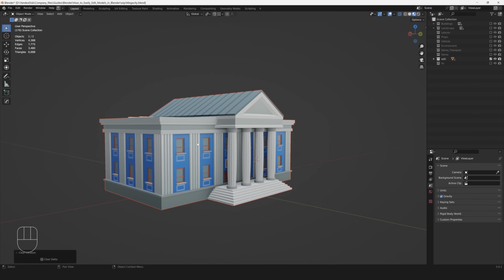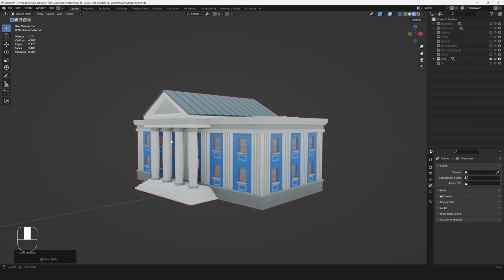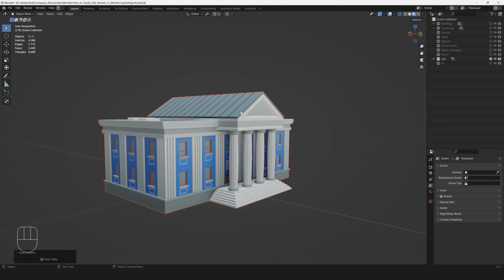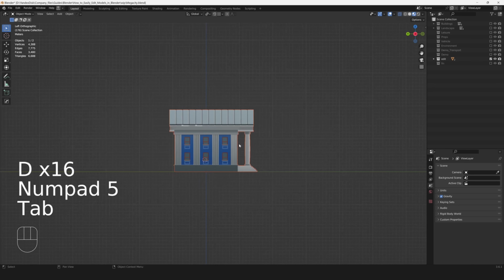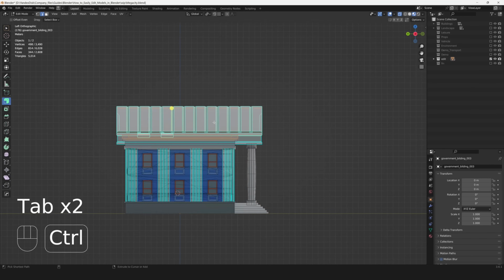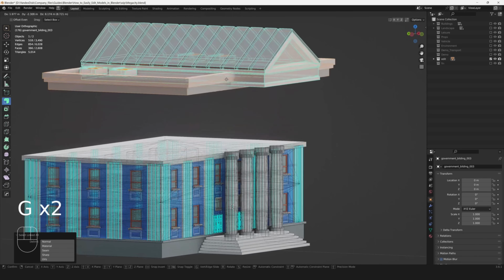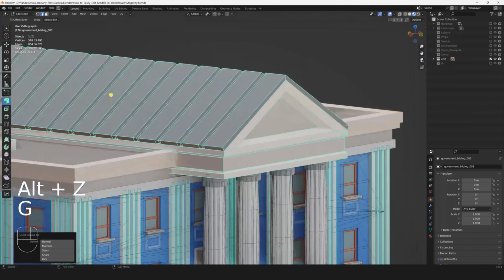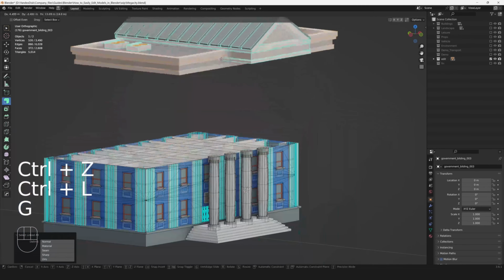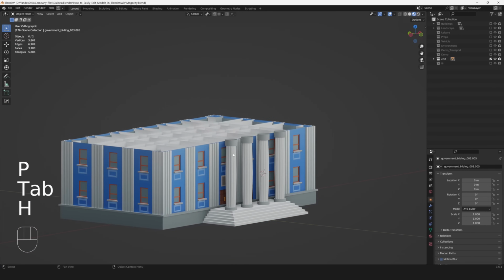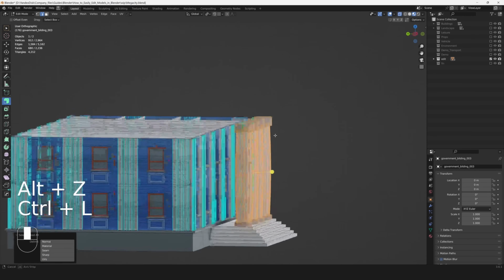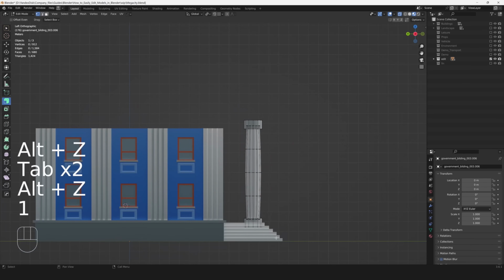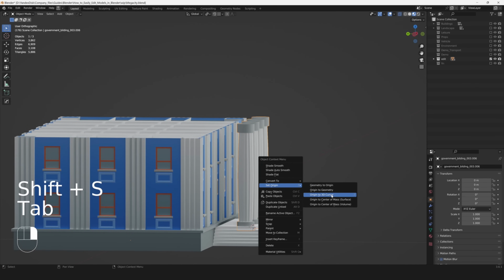For this building I want to have a second floor. As you can see, there are some elements that we won't be changing, like columns or roof. So let's separate them for now, because we don't need to change them. Again, we can select this geometry and move it around to see if I selected it correctly. With key H, I can hide the objects that are not necessary. In orthogonal transparent mode, I select all of these columns. Then I am easily selecting all of the columns on the wall sides.